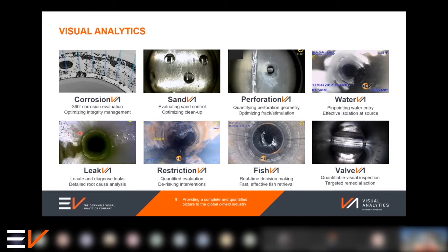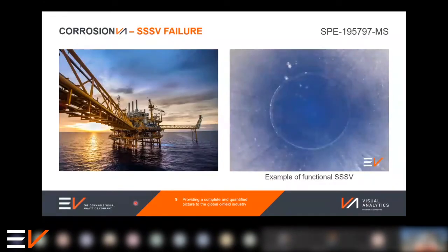And the first one I want to walk you through today comes from an offshore operator in the Mediterranean off the coast of North Africa, who was operating a high pressure, high temperature gas condensate field. Now, they performed a check of their safety valve performance, but unfortunately, they were having issues in getting that to seal. In fact, they weren't entirely sure whether it was moving at all, whether there's any functionality of the system, whether the flow tube was moving or whether the flapper was moving successfully.